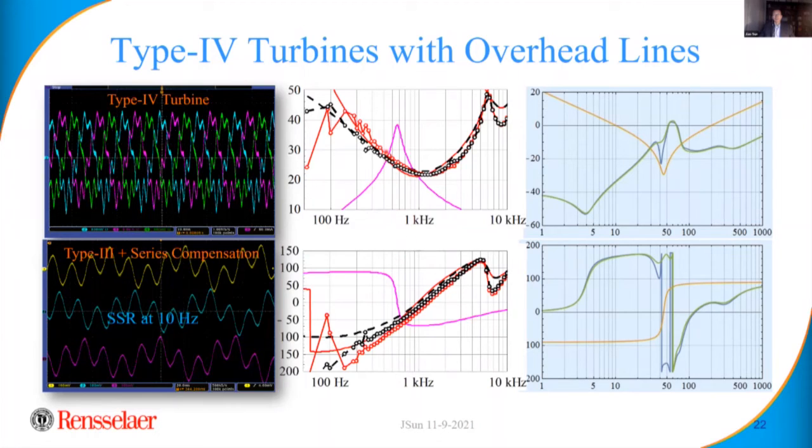And at the intersection frequency, we can look at the phase difference. The phase difference can tell us whether the system encircles the -1 point, or whether the system has enough phase margin. So this is a common technique we apply to analyze the operation of the system, right?